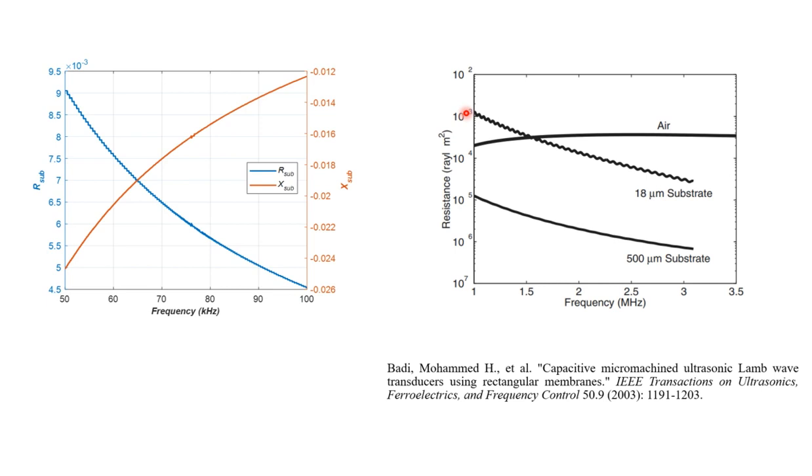So they talk of Lamb waves, and they exploit the power that the harmonically excited membrane couples to the medium in the form of Lamb waves, so it becomes a Lamb wave device. But the radiation resistance that these waves suffer is very similar to what we have for thin substrates, if you think of it in terms of elastic waves.